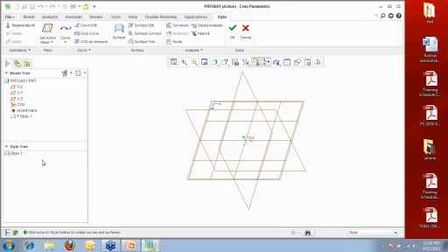They're all real-time regenerating within my ISDX feature, and so I can create curves, put a surface on it, but then come back and edit that curve, and I will see the surface update real-time as I'm dragging because, again, we're all within one feature and not multiple features within the model tree. Okay? So just some ideas conceptually about how it works.